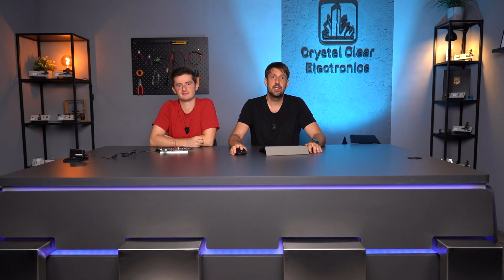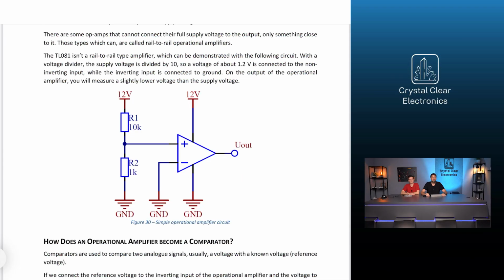Some operational amplifiers' output can't fully reach the supply voltage, which means that the maximum output voltage is slightly less than the positive supply voltage, and the minimum is a bit more than the negative. The types whose outputs can reach the supply voltages are called rail-to-rail operational amplifiers. The TL081 is not a rail-to-rail op-amp.